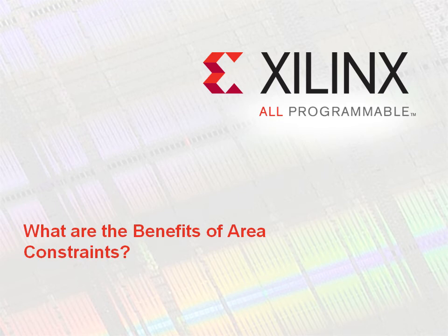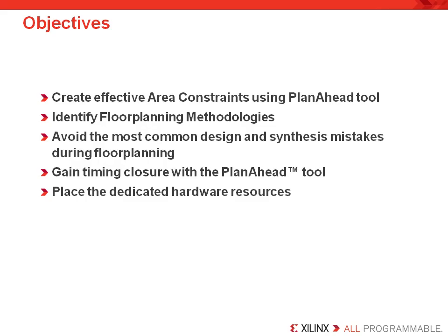In this module, we will learn about the basics of area constraints and their benefits. We will also learn how to make effective area constraints using the Plan Ahead tool. After completing this module, you will be able to create effective area constraints using the Plan Ahead tool, identify floor planning methodologies, avoid the most common design and synthesis mistakes that make floor planning and gaining timing closure with the Plan Ahead tool difficult. And you'll also learn how to place the dedicated hardware resources in the Plan Ahead tool.